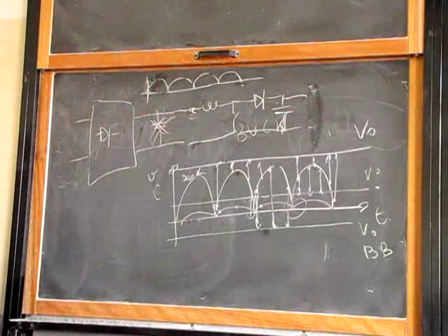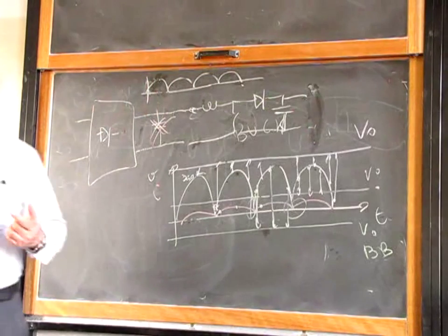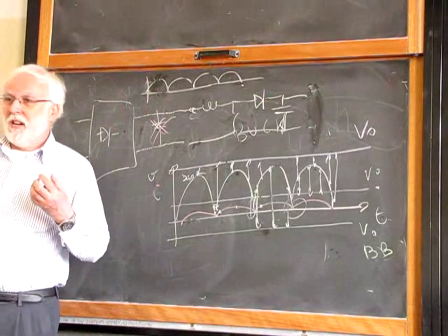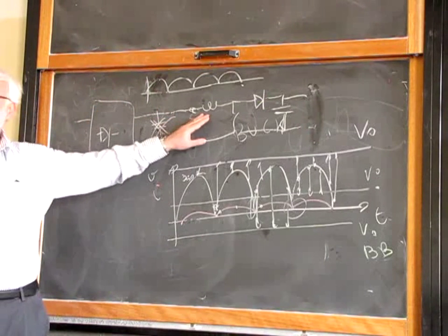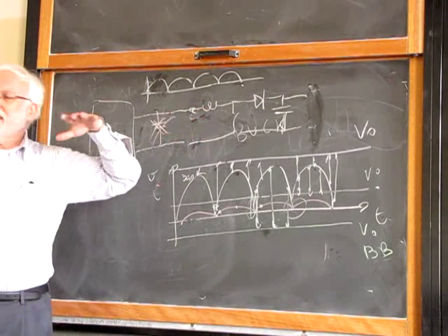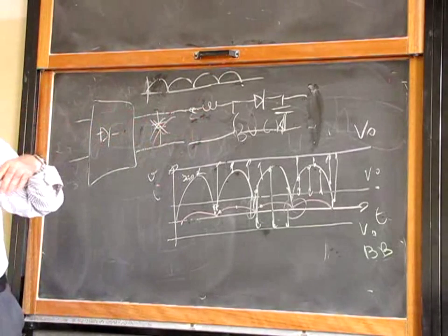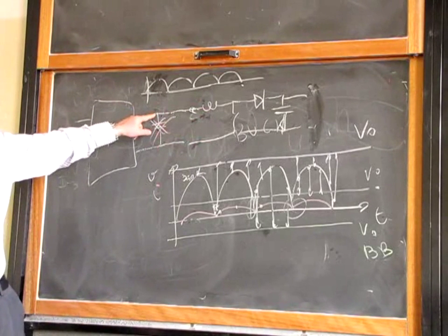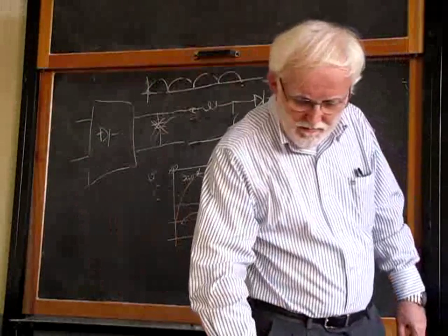The problem of a buck-boost converter, if you use a buck-boost converter as a PFC, is that a buck-boost converter has a pulsating input current. It takes a pulsating input current, and the pulsating input current over here generates a lot of noise. A boost converter is better, because a boost converter has an inductor in series at the input, so the input is cleaner, more quiet than a buck-boost converter. A buck-boost converter can have very stressful and very noisy current at the input. So in general, people go for a boost converter for a PFC.